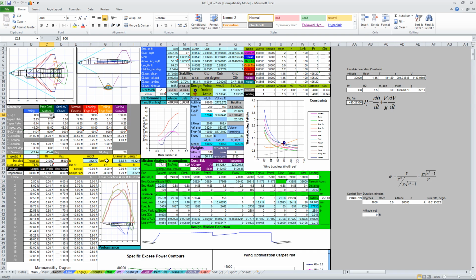On the other hand, we might be worried that removing that pitch control surface will make the aircraft very unstable. Right now, Jet shows estimates that the aircraft static margin is minus 3.7%, and that's probably a pretty good estimate for the actual aircraft. So if we remove that pitch control surface, what's going to happen? Well, let's watch cell M10 while we set the pitch control surface area to 0.001.